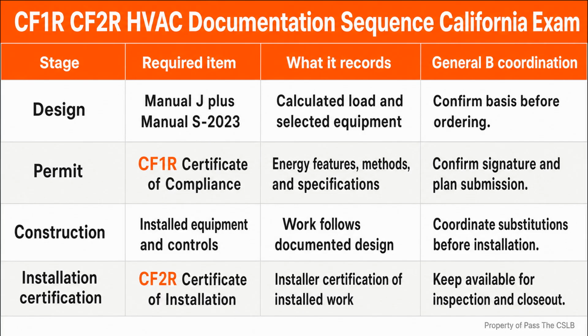Second, suppose equipment arrives before anyone can produce the load calculation or the Manual S selection. The schedule is tight and the crew wants to set the unit anyway. I would place the installation on hold. The immediate inconvenience is smaller than the rework risk created by installing equipment that may not match the documented load.